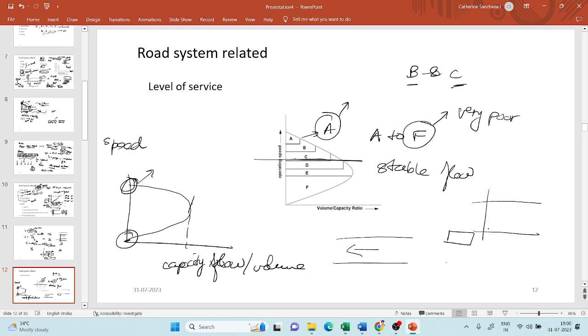So when I stand at this cross section, say if there's a traffic jam and you're trying to count the number of vehicles passing this section of the road, how will you be able to count if there's no movement? If there's a traffic jam, the vehicles are going to remain stagnant, which means there's not going to be any movement across this section. In that case also, the flow is zero and the speed is zero. So these are the extreme cases.